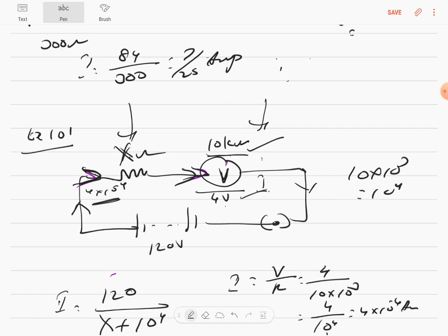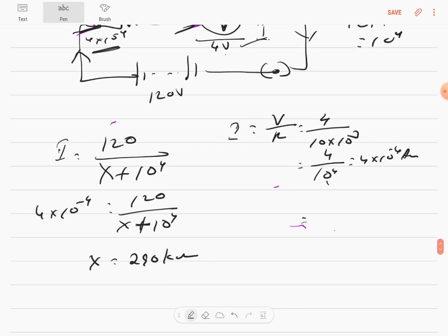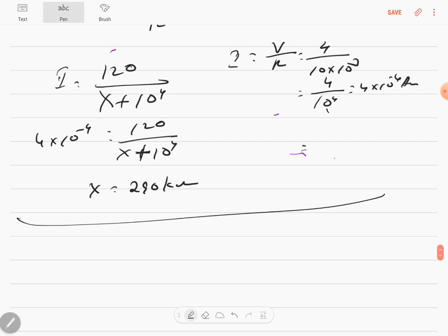Whenever in a circuit there is a negligible current, so that's an MCQ, and you can't measure it using an ammeter, then you can put a voltmeter, whose deflection will be seen. And only if you know the inbuilt resistance of the voltmeter can you put it in series and thus know the value of the current there. This is an indirect way of measuring the current in the circuit if the current is very, very low. So that's this, which is an NCERT sum, which is beautiful.